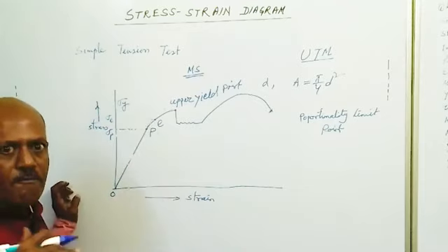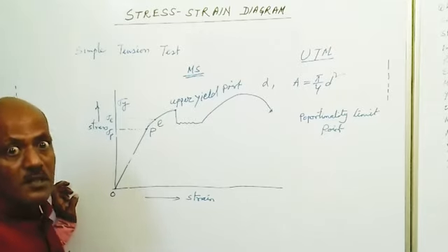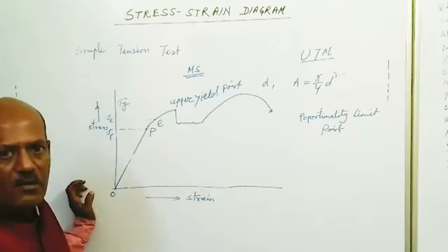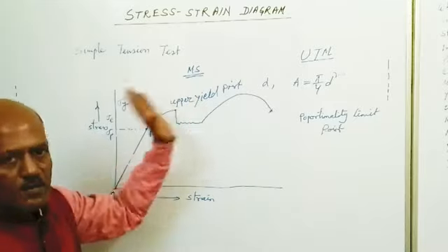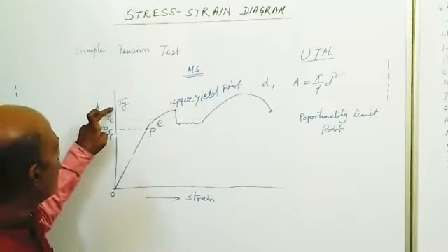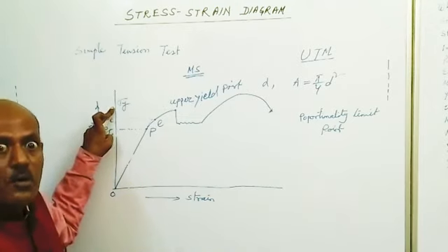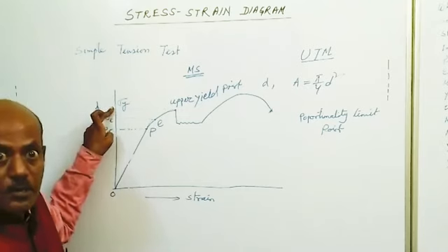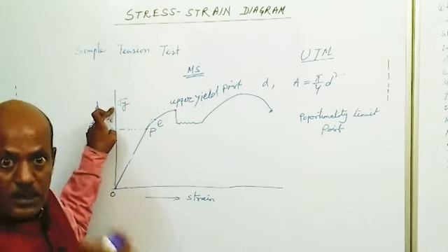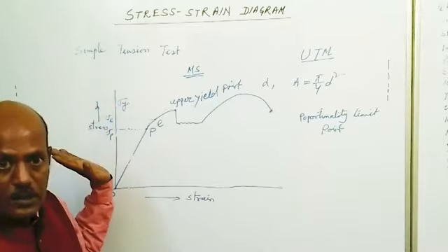So this is the upper bound condition or upper limit. If we cross this limit, then further phenomena will happen, otherwise this phenomena will not take place. So if we cross this value, that is sigma y into the original cross sectional area, that much load if we apply over the body, beyond that only the further phenomena will take place.